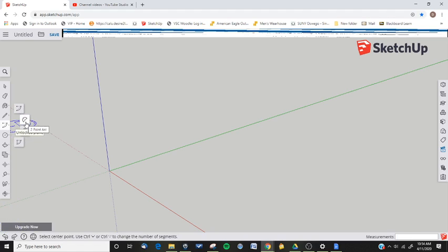Next, we have our 2-point arc, and again, coming right from the good old Google SketchUp page. Our 2-point arc is defined as this tool can click to set 2 points and then drag out essentially the arc aspect of it to create the arc. So let's do that. So we select our 2-point arc, we choose 2 points, and this is our base measurement here. It can be the diameter to a certain extent, but it doesn't necessarily have to be. So there's my second one.